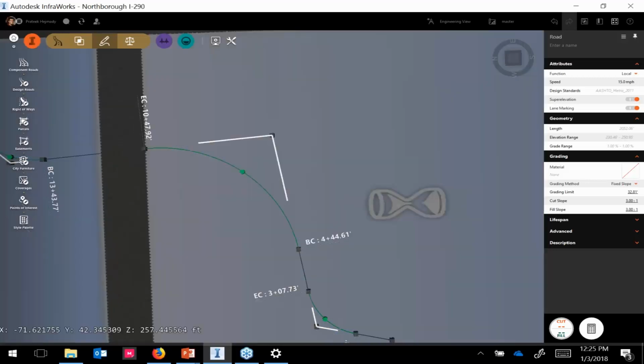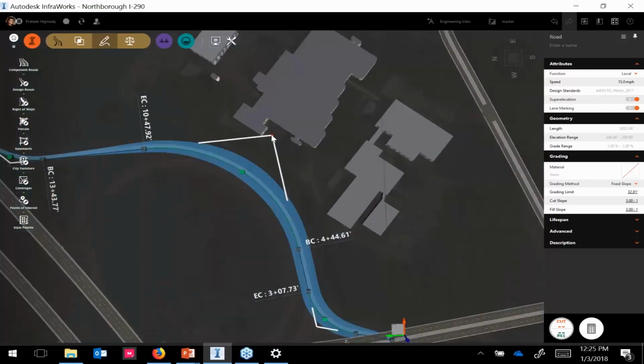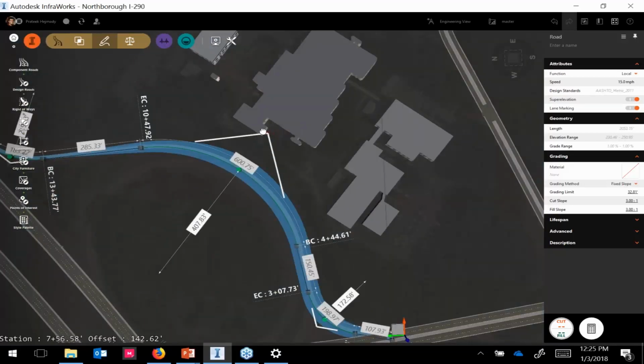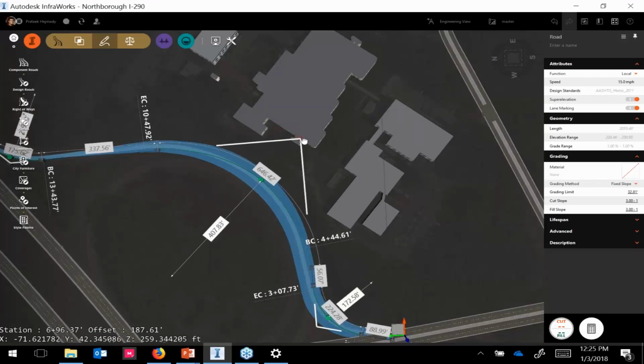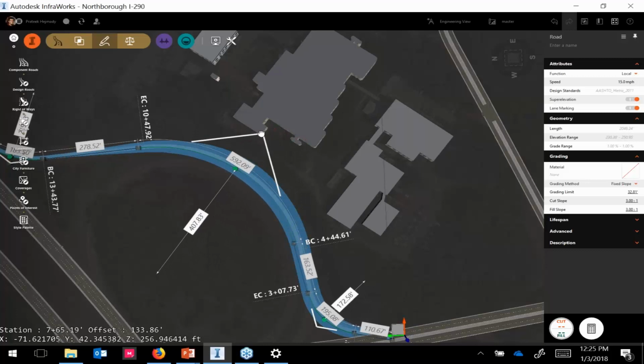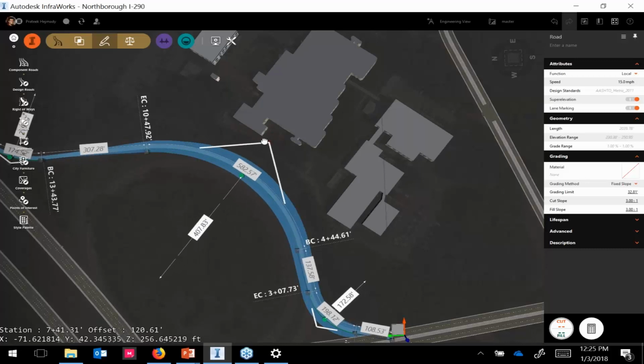So I'm just going to go ahead and place it there. I could also move the geometry as a whole. I could select this PI. If you see, it's maintaining the radius of the curve that I've selected and letting me move it as a whole. However, that also means some of the other geometries are going to get impacted. See further down the line, the curve at the bottom is also getting impacted because of this move.